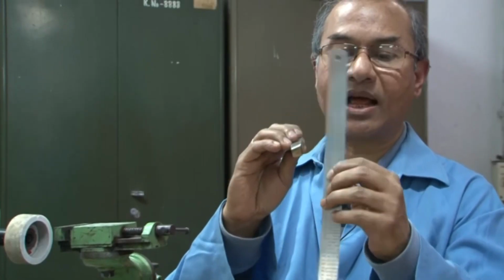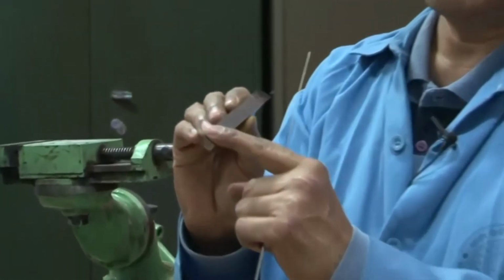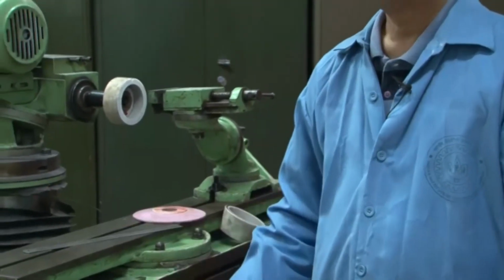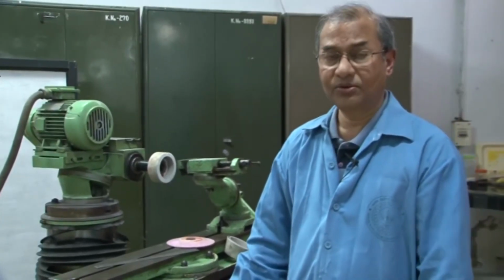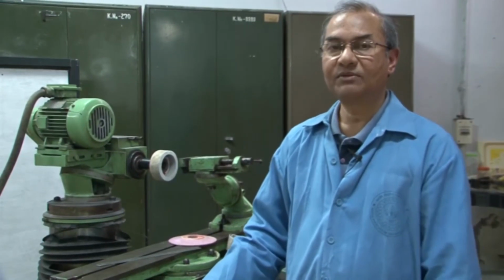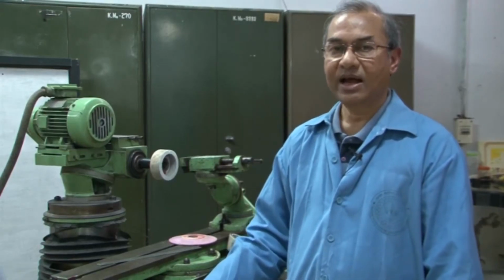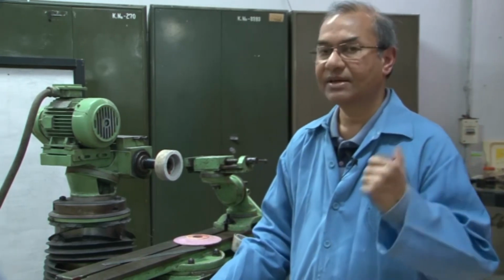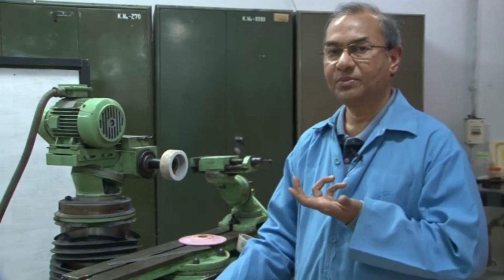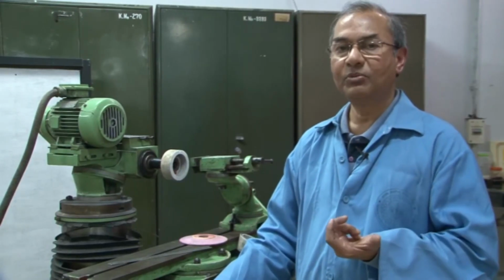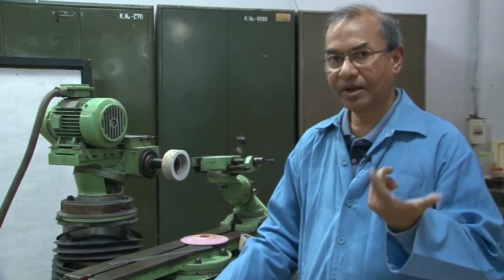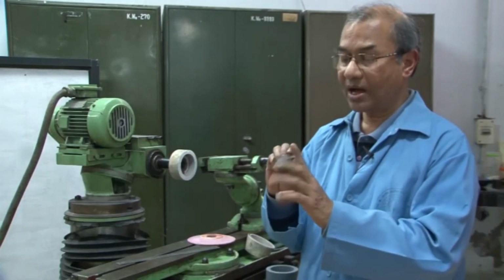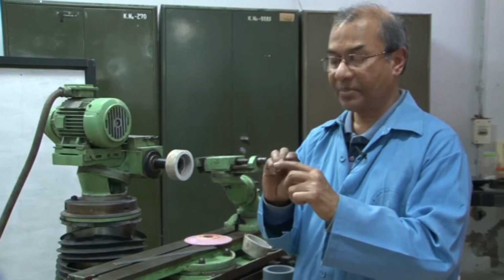So, this side rake angle defines the inclination of the rake face, and as I already told you in the lectures of the course, the side rake angle is one of the important angles, because it also defines the cutting power and the cutting force, meaning that if the side rake angle is changed, the cutting forces will change and ultimately the power will change. Those details have been given in the lectures, which you can see. We will show you how this angle can be ground.